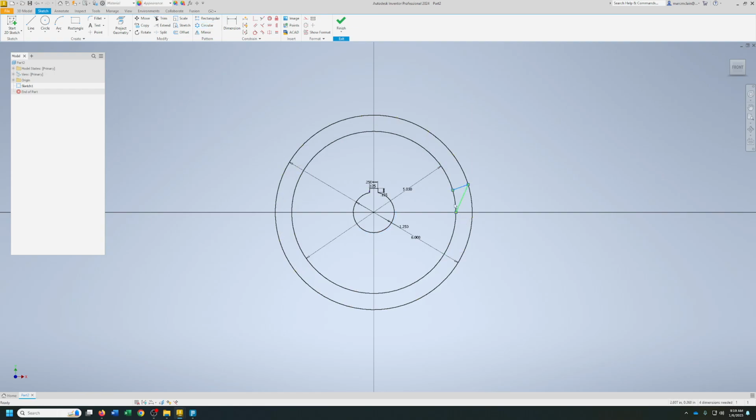So I'm going to cancel that, draw this line back in. I'm going to extend this one. Okay, see how it moved it? So we'll take that, we'll drag it out, and we'll draw it back. You can see my degrees right there. So I'm just going to go ahead and just hit tab, type 20. And there we go. That's what's nice about having that preview.